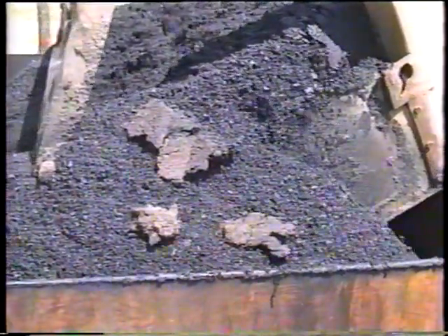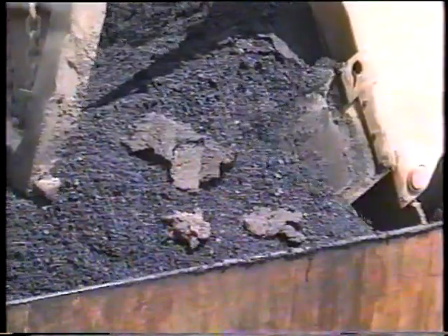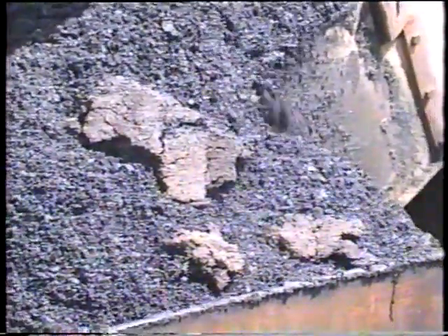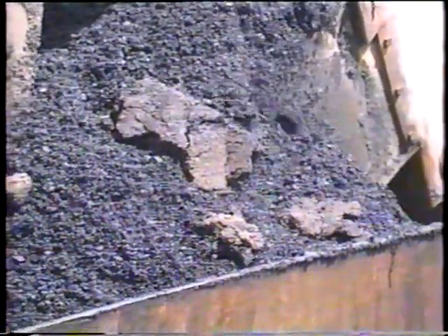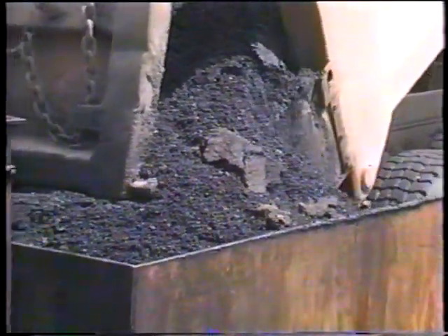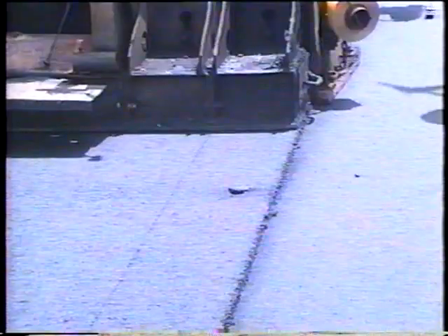On the other hand, if the mix is too cold, the air or surface temperatures are too low, or the haul is too long, the results aren't too pretty. Lumps in the mix are a good sign that the mix is too cold. Lumps can also be caused by improper mixing. In either case, the lumps themselves present a problem. They aren't shaped by the screed, and they can't be rolled out. So they remain separate from the surrounding mix, causing weak spots in the mat. Try to catch them before they get to the mat. Otherwise, they must be dug out and replaced by hand.